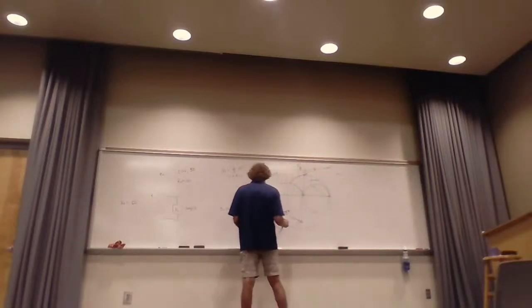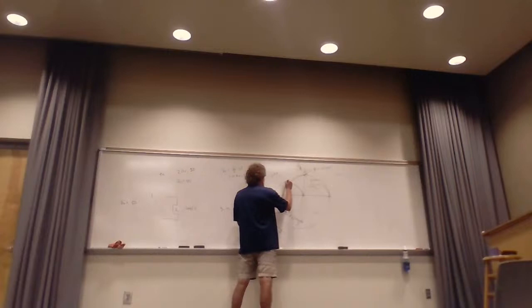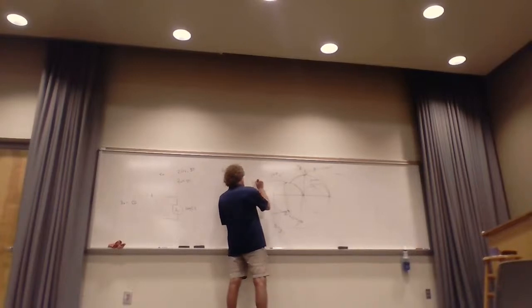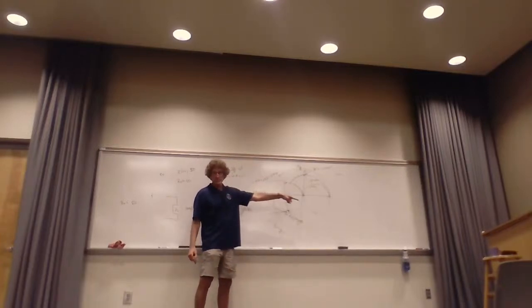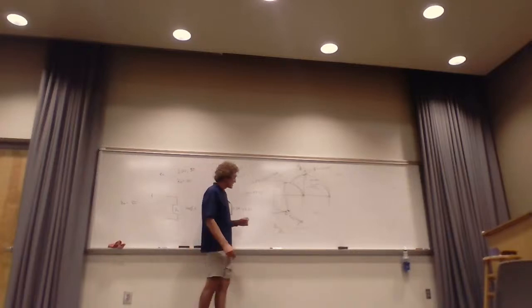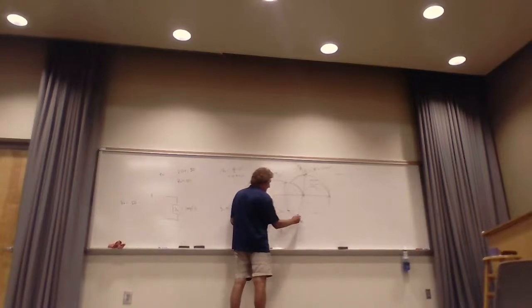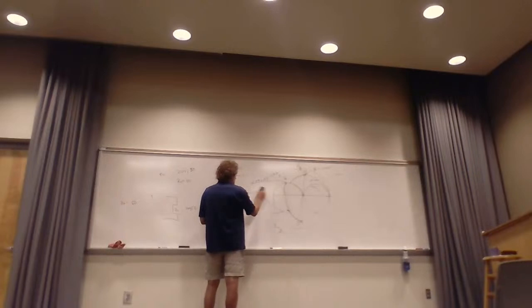So that's not going to be, if this is 0.34 minus j0.5, this point up here, I want to move all the way up here, which will be 0.34 plus j0.51, right? And I want to move to there because I want an inductor. Wait a second. Yeah, we're in the admittance domain. So that's my 0.2. That isn't 0.3. I'm going to move all the way to here. Here's my 0.3, and this is the value right here.